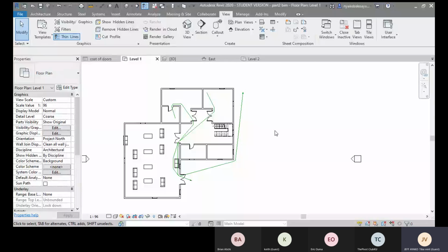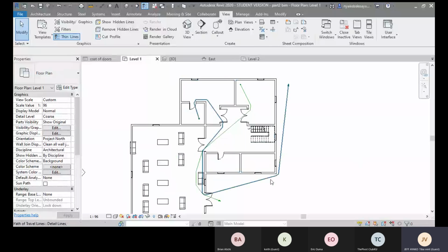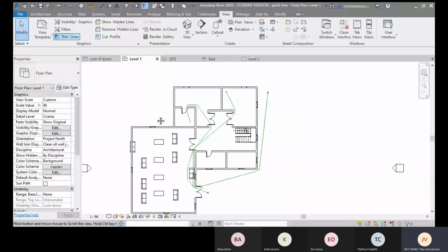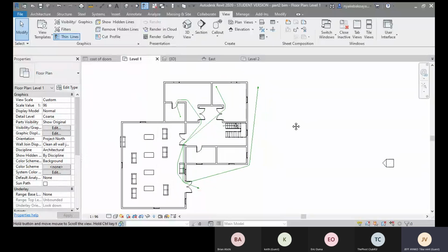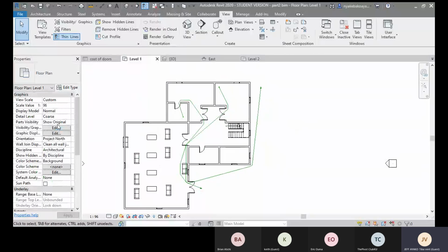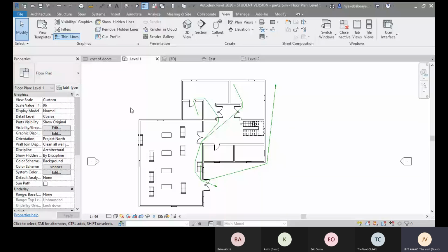There will be differences in the sense that if we take the approach of area, area only applies where you have uniform wall thickness, like these exterior walls and all of those. But sometimes area will not work, for example, where your interior walls are thinner, where the outside uses a 9-inch wall and then inside here you use a 6-inch. That method you can't apply, so you need to do it by volume. But okay, let's move this one inside there.